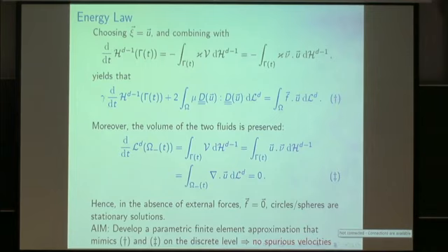And that was, for many years, actually an issue in engineering science, where numerical methods did not satisfy these properties. And so what then happens is that you get so-called spurious velocities. So these are velocities that you see in your numerics, which you just know shouldn't be there, because you know that your circular bubble should just be stationary, and nothing should happen. Velocity should be zero, and just in your numerical method, you see these velocities which you know must be spurious, down to discretization problems. Question?